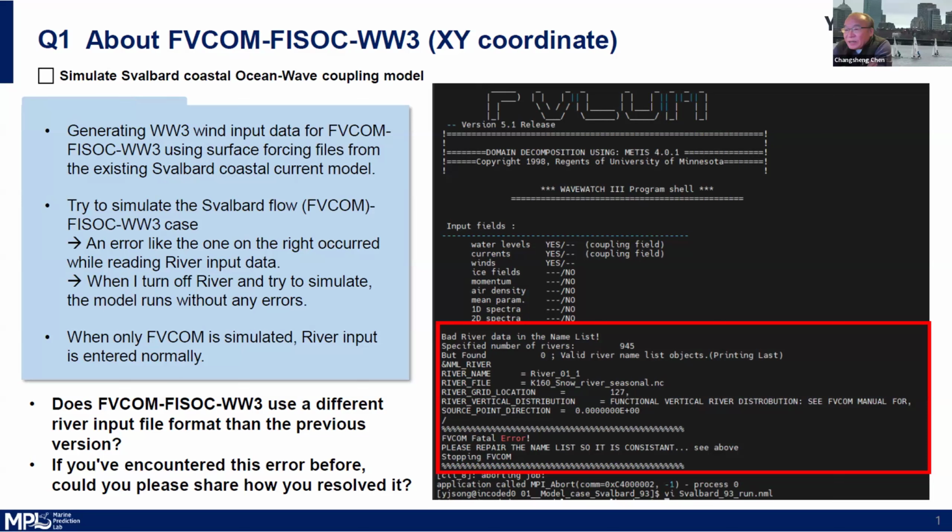One thing I can add: you may not have the updated code yet, but Dr. Lu Wang found a problem when the water becomes shallow. Radiation stress can run into trouble, because the equation has something divided by a tangent function of theta that can go to zero, since the wave number times the depth d can go to zero.